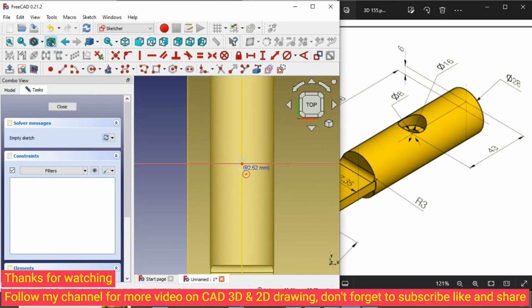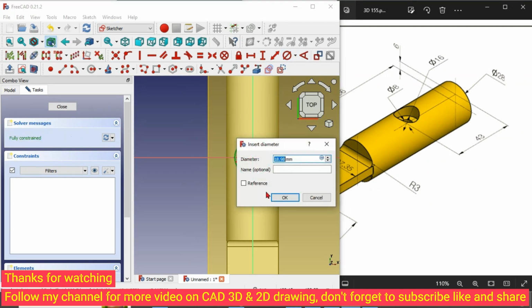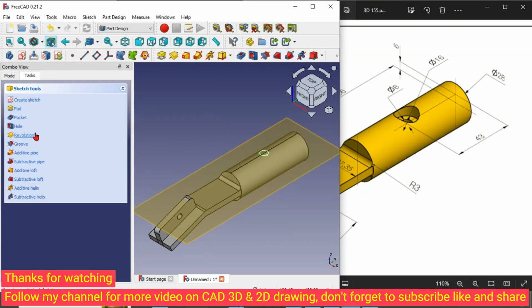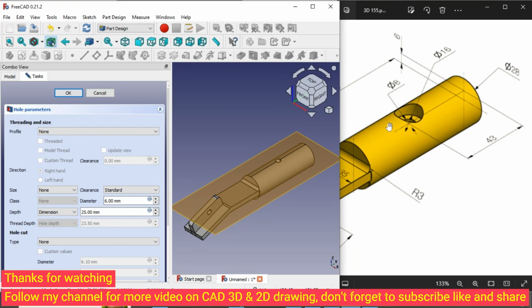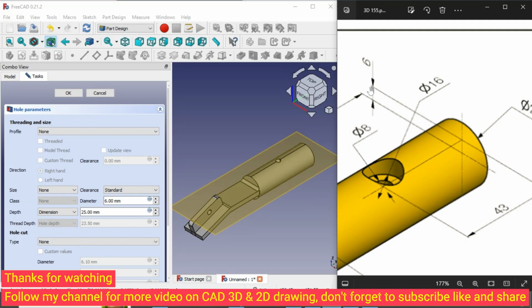So we draw a circle, then we set the diameter to be 8. Okay, close. Now we click hole. It's different from FreeCAD. Okay, we need to decide what we want to do, because if you see from the drawing, it has the first hole and also the second hole. The first hole is diameter 16. The inner hole will be diameter 8. The height here will be 6.